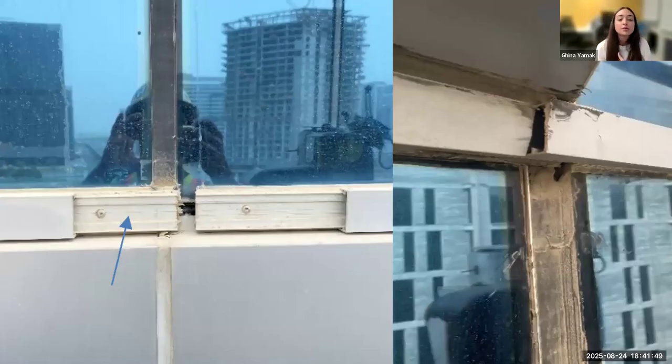On the image on the right, you can see that the transom pressure cap piece is just not aligned. Again, they just decided to do that, or it's just poor installation, or sometimes scraps being there and they just want to install it, or maybe it's just poor installation and not monitored and reviewed well by a consultant later on site with a proper QA/QC. So we encounter a lot of those issues on site, especially with the old buildings, where I would say there wasn't maybe a proper system for a consultant to be on site and review the contractor's work and make sure that whatever we delivered as a design is properly done on site.